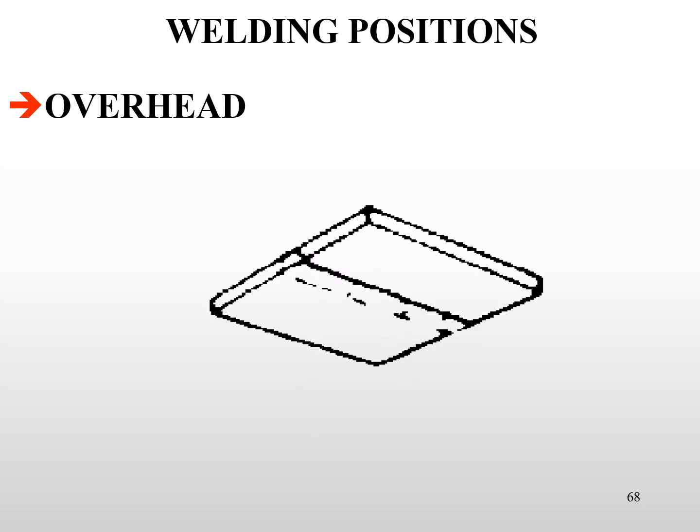The overhead weld, my least favorite, because everything's taking place above you, and anything that falls from this type of welding is going to fall right on top of you. Therefore, your gear and equipment must be correct to keep you from being burned.